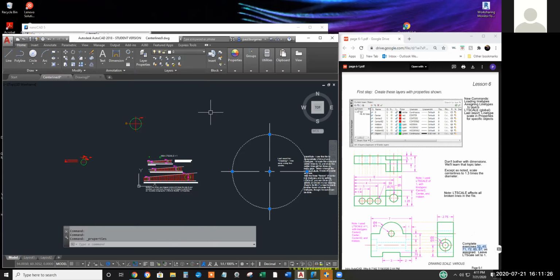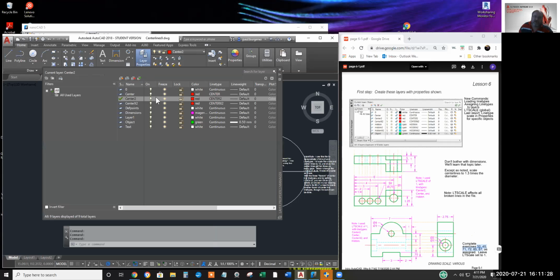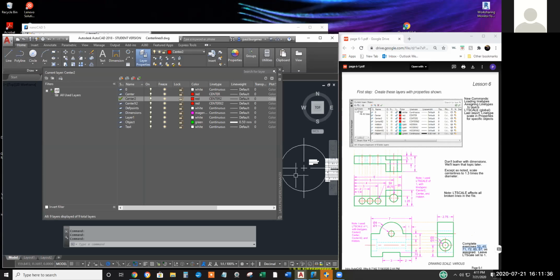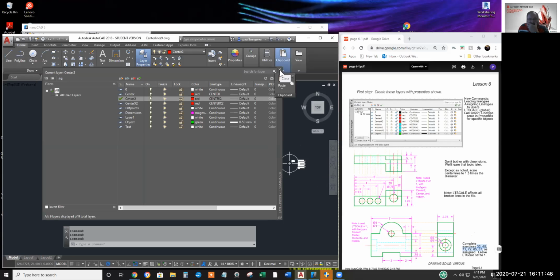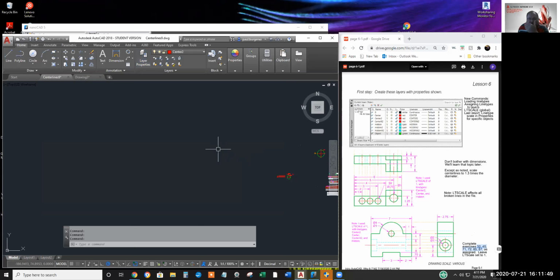Now, I don't think it's such an issue for the hidden line types. Well, sometimes the dashed lines don't show up in viewports that I created, and I have to play with the scale on those too. I understand, but nobody's going to care if a hidden line has 8 dashes or 12 dashes, as long as you can see the dashes. Right, the precision doesn't have to be the same as a circle.